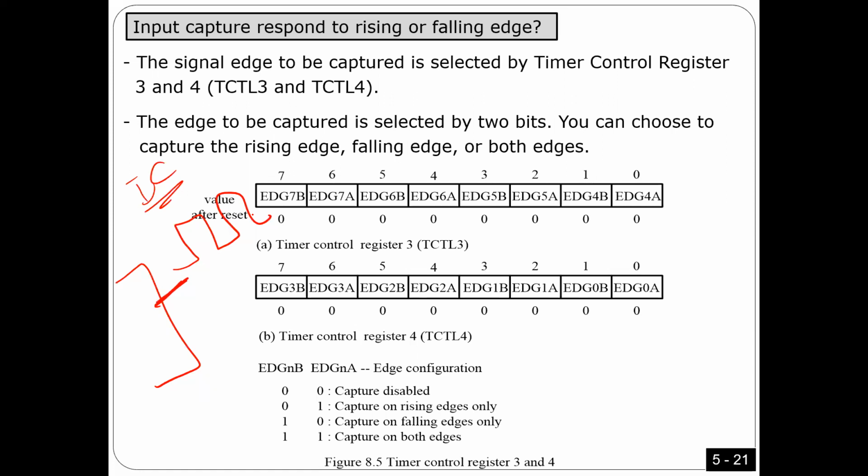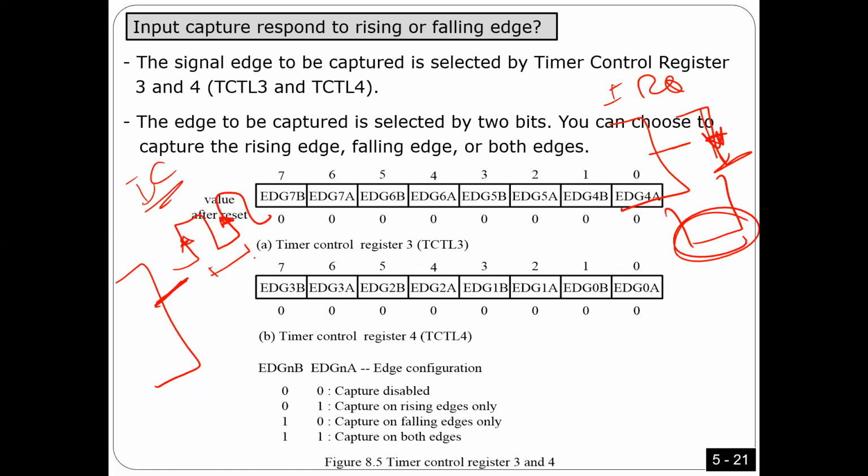Similar to IRQ, you remember IRQ, there was initialization, and you could capture falling edge, or you could capture low level, zero level. These were the two options I had in IRQ. Now I have different options here. You can capture only rising, so I'm going to measure the time from here to here. You can capture only falling. You can capture both rising and falling.